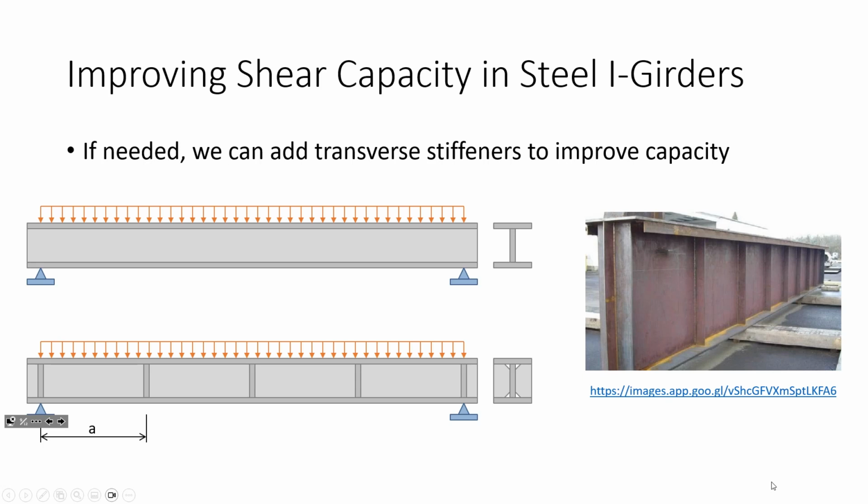You will see stiffeners all over the place. You'll see oodles and oodles of them, because back in the day, labor was somewhat cheap in comparison to the materials. The materials were very expensive. So we were trying to shave every single pound of steel that we could off the bridge. And the way that we handled that is to just throw stiffeners everywhere.